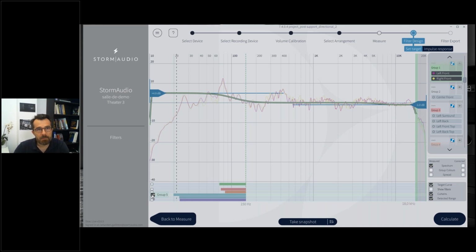It is more important to do it in the main subwoofers group adjustment, because this is where the LFE signal comes, and we know there is extremely low frequency content. I am not too sure about the other signals. The mixers put a lot of low energy below 20 Hertz. So in that case, I'm not sure selecting the infra bass is going to make a difference.